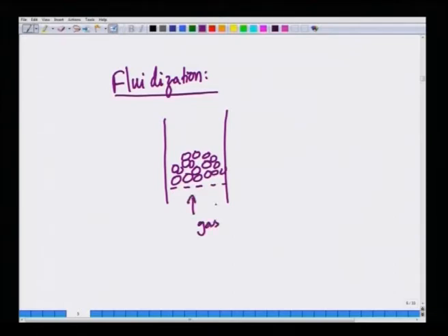Okay. So, initially it is a packed bed. Initially, the weight of the particles acts downwards, gravity is acting downwards, and is balanced by the pressure drop. Okay. The pressure drop that you exert to make the fluid flow is essentially balanced by the weight of the particles. Okay. If you do a macroscopic momentum balance, that is what will show up. Okay. If you take this entire thing as the control volume,